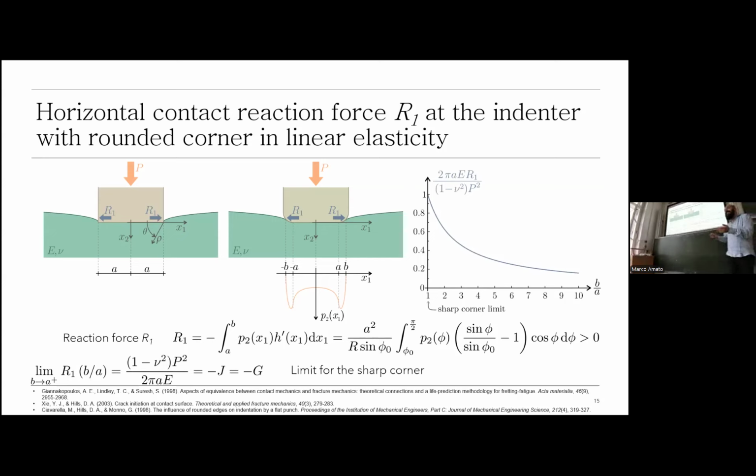We can conclude that even if the J integral was already investigated in indentation problems in linear elasticity, it was never related to the energy release rate associated with a horizontal growth of the punch, and on top of that, it was never related to the horizontal component of the contact reaction force. These results, this non-accidental coincidence, invite us to study this concept also in the nonlinear regime.